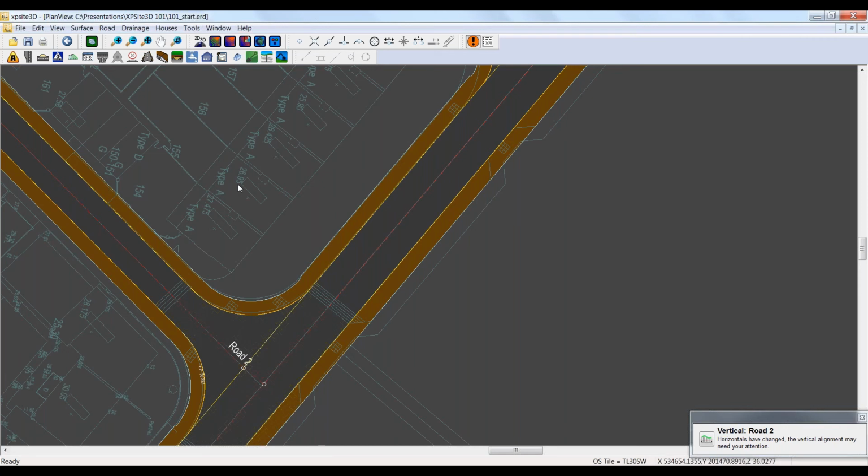We want the bus stop to be draining. We want the rainfall that lands off it to run off it into the carriageway. So two more complicated things. One is a more complicated shape, and the other is the manipulation of the gradients on the carriageway. So to do that, I'm now going to use a secondary channel, and I'm going to create a new secondary channel. Again, it's asking me front or back, pick the front.